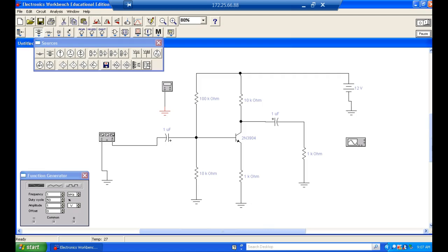We have several options, guys. We could change the collector resistor. But if we raise that resistor to make it drop more voltage, then we increase the output impedance of the amplifier, which means we won't be able to get as much out, right? So my option would be over on the base side.